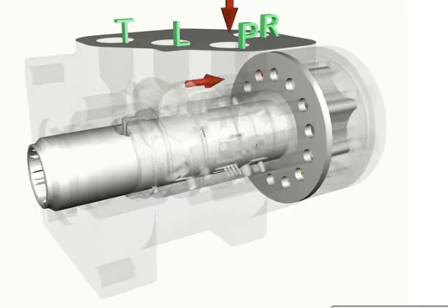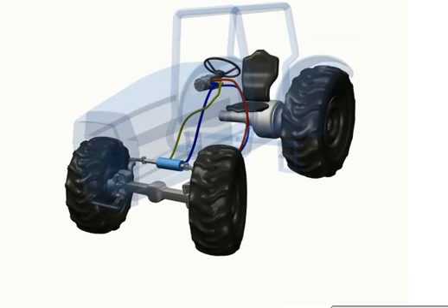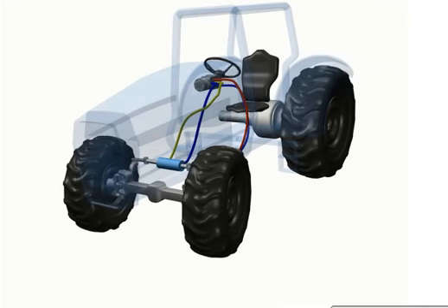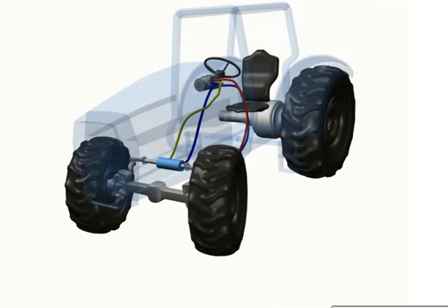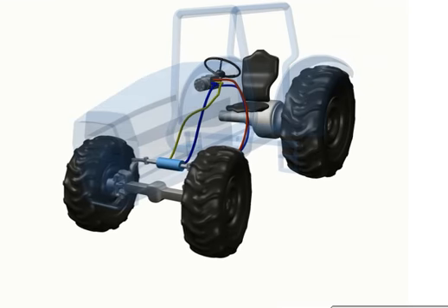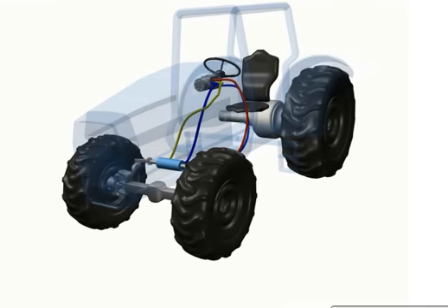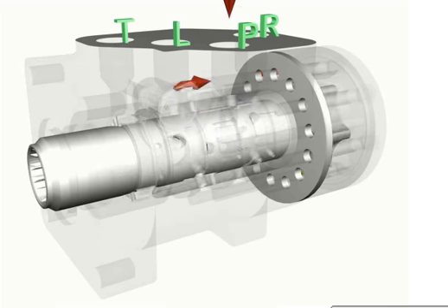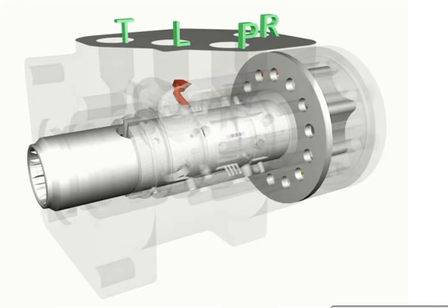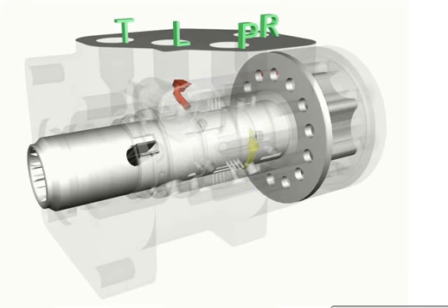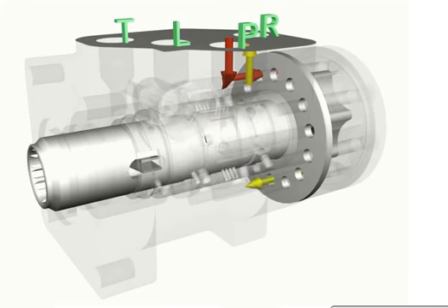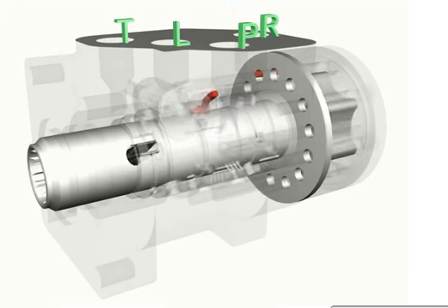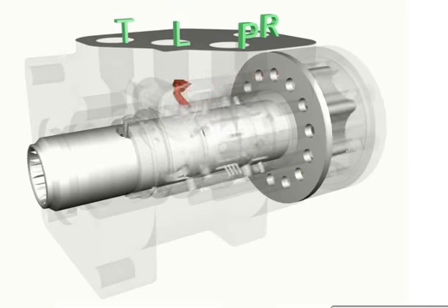Fluid flows through the unit and turns the wheels in the opposite direction. Pump flow not used in the steering circuit passes through the tank port of the unit to the reservoir and to other downstream functions through the power beyond port of the unit if provisions are made for this option.